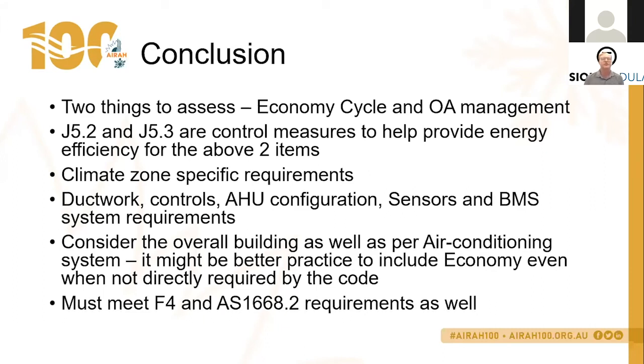What's the best control method for economy cycle, enthalpy or dry bulb temperature? The best method is enthalpy control, because you are controlling the humidity as well.